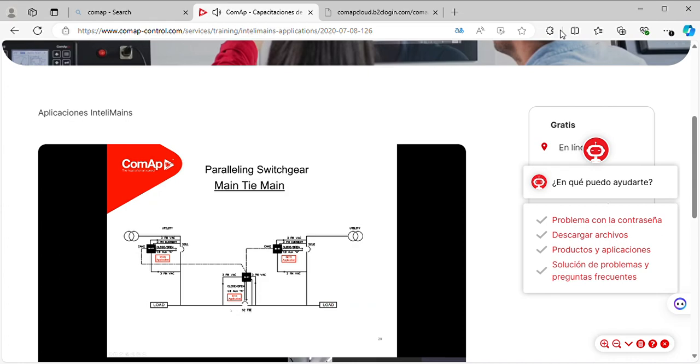And this bus tie breaker is good to synchronize between the common bus, between the gensets. It does not perform synchronization between utilities. So if suppose one utility is down, it will basically open up the MCB and close the BTB here and feed the power from the second utility to the load on the left hand side or right hand side accordingly. So how does this happen?